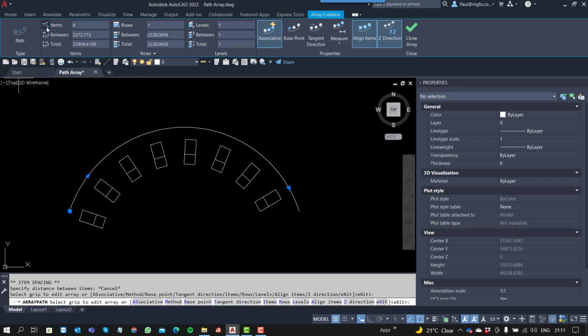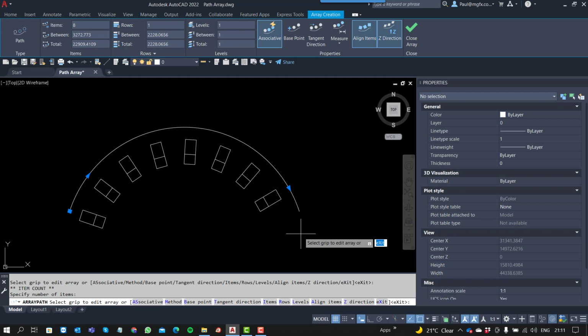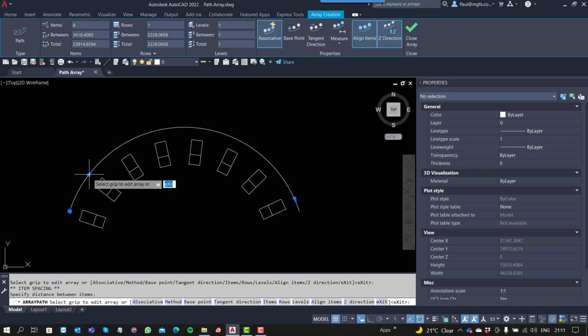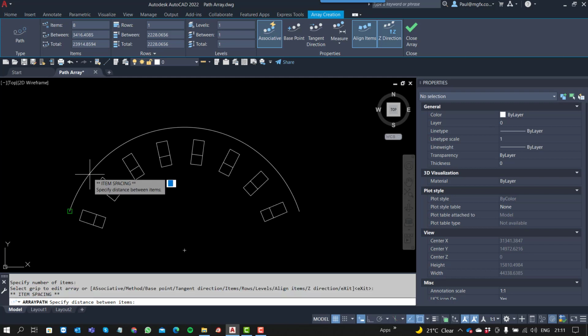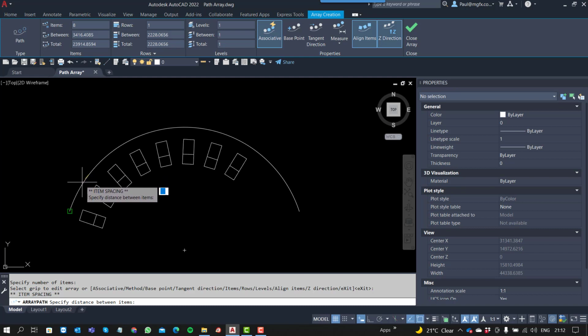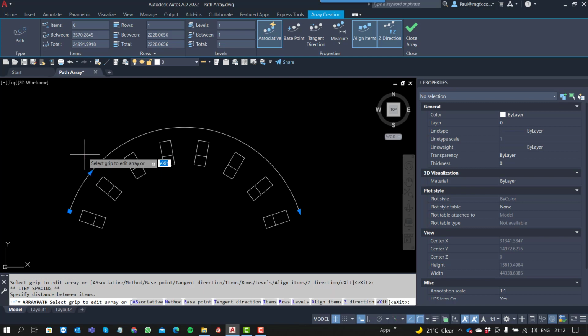Once this is untoggled, you will see that there is now an endpoint to the array where you can bring that to the end. And again, it doesn't exactly set that number. If you move this on a bit and then try the same thing, it's still not working. But as you push this along towards the end, it now sticks. So you're able to push these items along until it sticks, provided you've indicated the number of items.